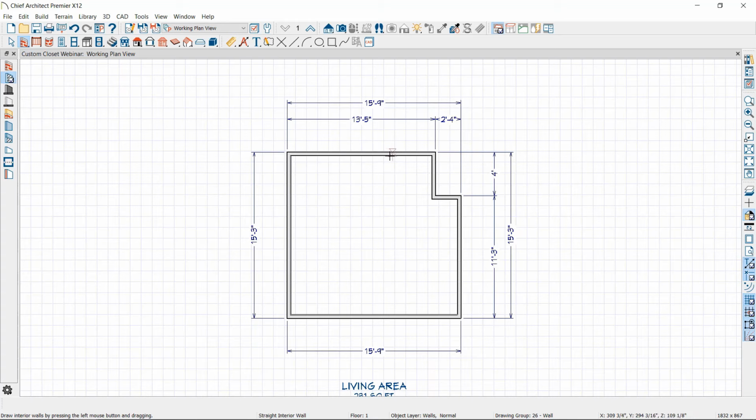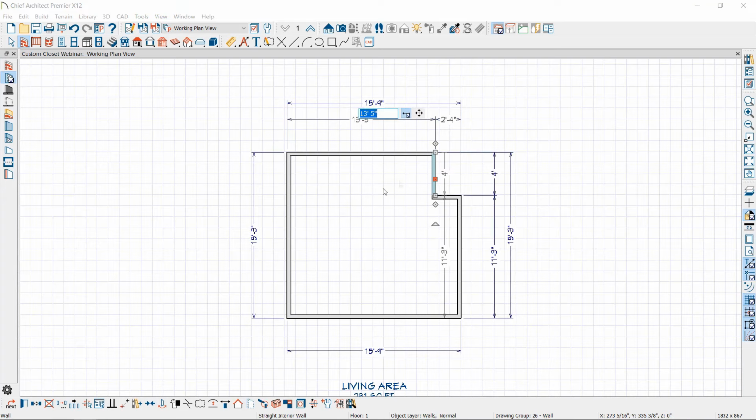So we have a couple of options to dimension this. I can select a wall that I want to change the dimension, or I can select a perpendicular wall to the dimension, the wall that's actually going to physically move in space, and then I'm just going to click right on that dimension and decide how long that wall is supposed to be. So let's say we're going to do 120 inches.